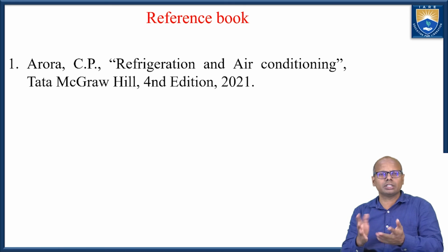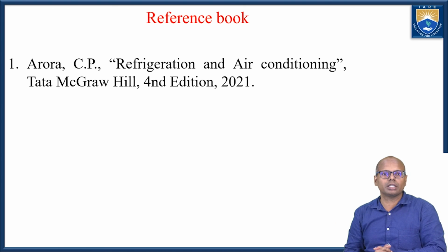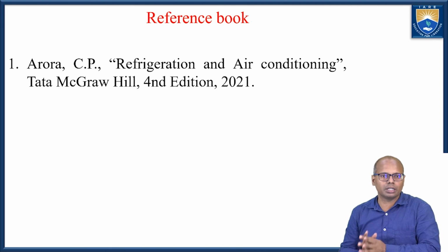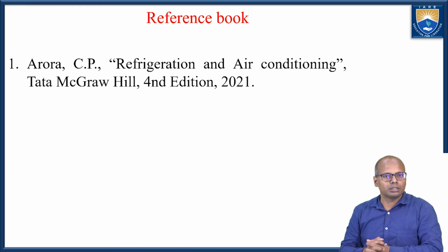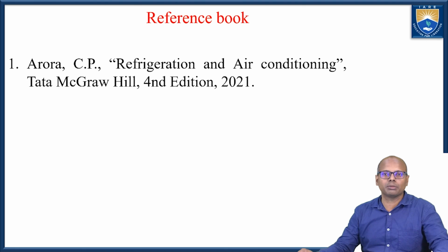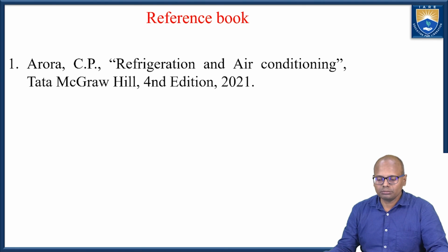And for the analysis, if we understand the concept and represent it in the TS diagram or the TH diagram, that is, the temperature-enthalpy diagram and the temperature-entropy diagram, I can easily find out the COP of the actual cycle and the ideal cycle. So, this is about the theoretical understanding of the vapor compression refrigeration system.